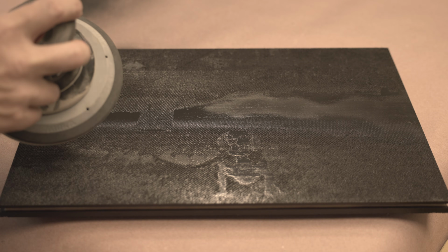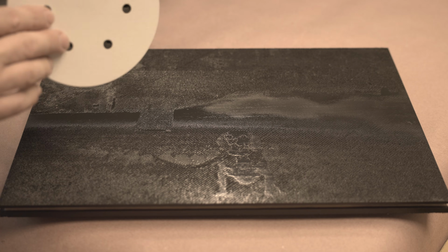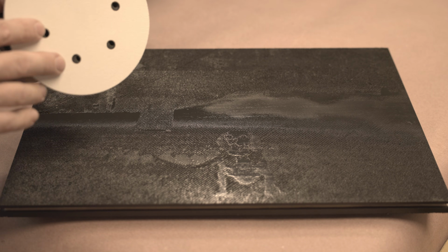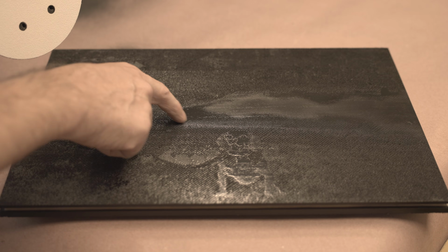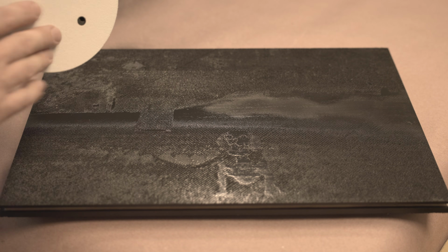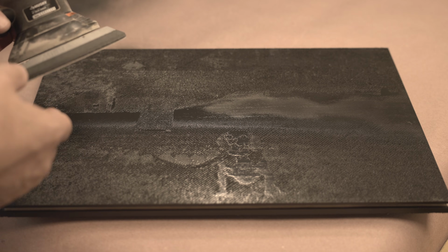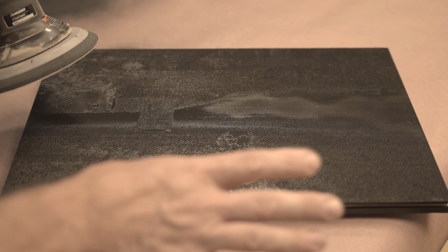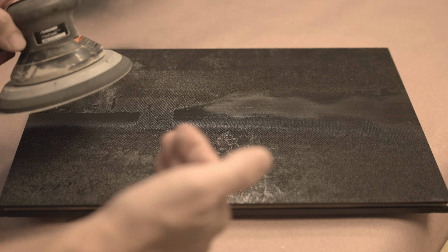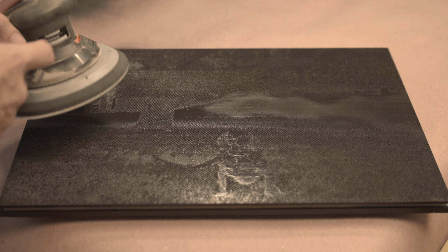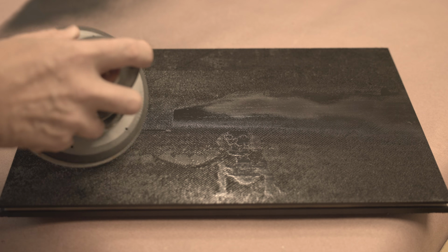All right, so I have an old piece of 100 grit on here. It might not be enough to get started because lacquer is very strong, very, very hard, durable. So I'll try it out, see what happens. I may switch to an 80 grit just to get the lacquer off quickly, and then switch to a finer grit. I probably won't go higher than 150 on the entire thing. So just so that you know that. All right.